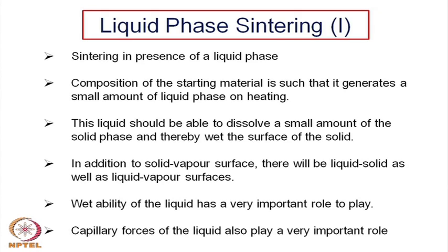In addition to solid vapor surfaces, because you have an additional phase, the liquid phase, there will be liquid solid as well as liquid vapor surfaces, and those energy terms are also to be considered while we are talking about liquid phase sintering. Wettability of this liquid phase, as I mentioned just now, has a very important role to play.